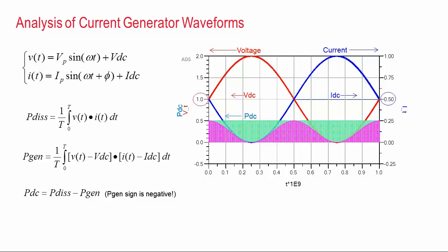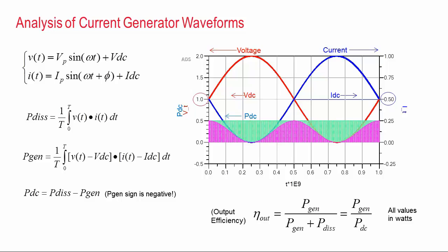So what I'm showing here are the waveforms for what's called a Class A power amplifier, and I just proved for this type of PA, at best half of the DC power will be converted to RF power. And as you might guess, this amplifier will be at most 50% efficient. So the concept of efficiency for a power amplifier should now be quite clear.